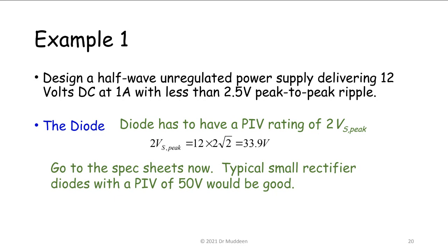You would give it at 50, because, for instance, the transformer is giving you 12 volts out, assuming, let's say, that the primary is giving you 120 volts in. There are times and places in Trinidad, for instance, where the voltage may go up to 124 volts. If the primary goes up to 124, the secondary is going to increase from 12 to something. If it increases to, just for argument's sake, 13 volts, then twice the peak is going to be 13